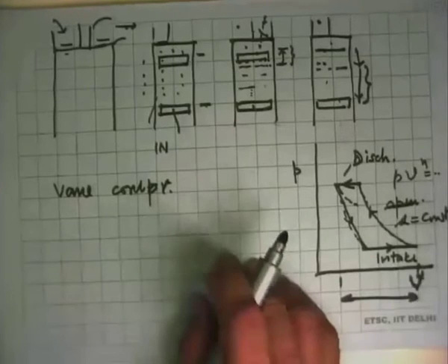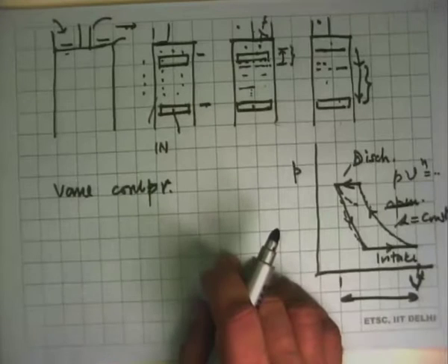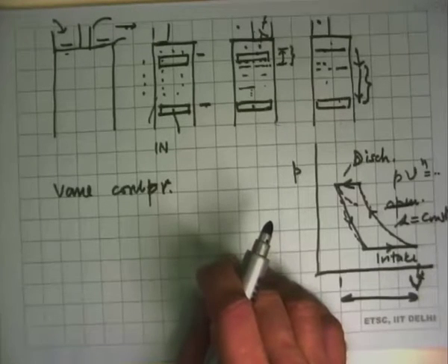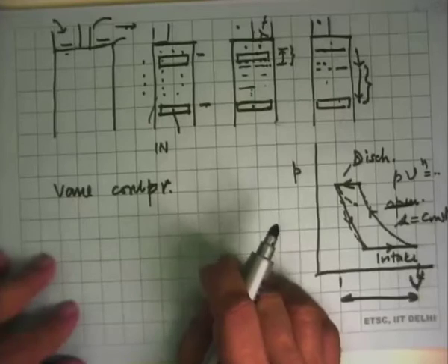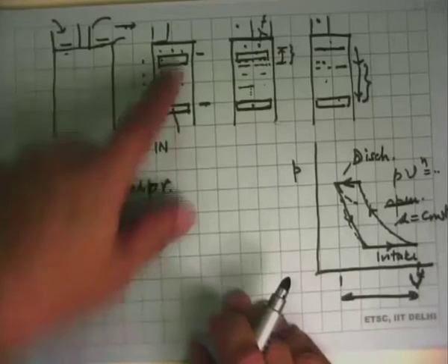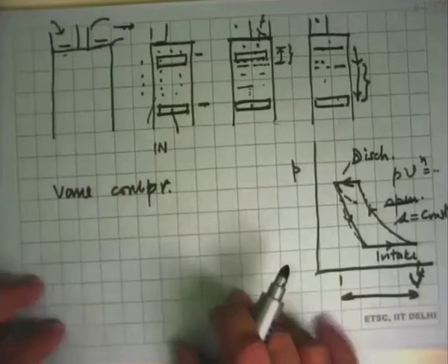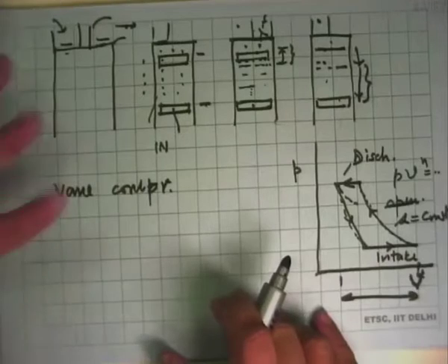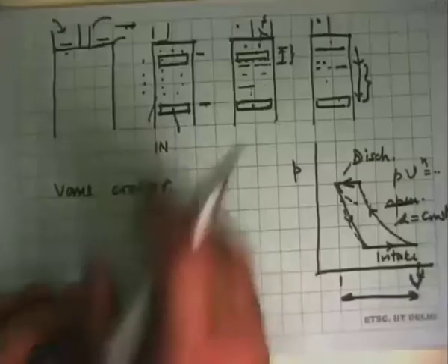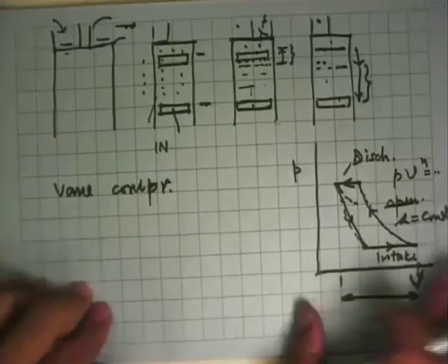In an aeroplane where the wings and the flaps are to be adjusted, that is done by giving force to a cylinder piston arrangement with high pressure oil in it, and that oil pressure is regulated by an electronic controller, which gets signals from the main flight computers. So that is one example. Another example where you have the liquid going in and out is what you may see in all your bulldozers and excavators, where the bucket goes in and scoops it out. Inside that long cylindrical thing is basically a cylinder piston arrangement in which you are putting not gas but compressed oil, and that does all the work for us. So all these analyses could be done from this type of system.